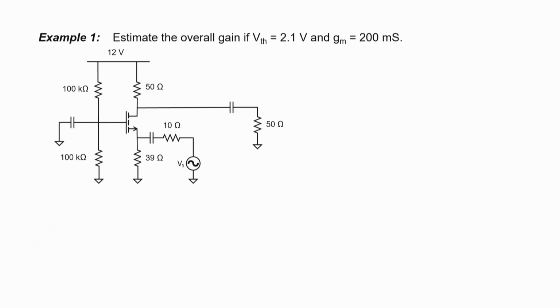I really like this one because there's only one thing that you have to remember that's not so easy to do by inspection. All you have to remember is that the gain part of the expression of the overall gain for a common gate amplifier is given by resistor RD divided by 1 over Gm, where Gm is the transconductance of the transistor. Let's work an example together and try to find the gain.